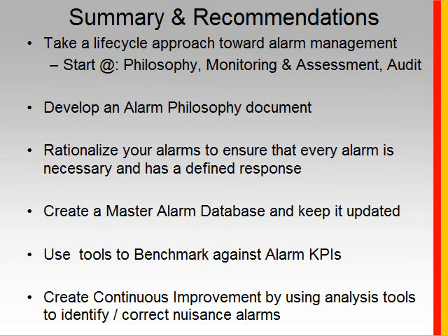It's also recommended to develop an alarm philosophy document and rationalize your alarms, so that you're continually making sure that alarms follow the cardinal rule, which is that every alarm requires an operator's response and is truly necessary. It's also recommended to create that master alarm database that you can use to keep track of all your approved alarm settings.